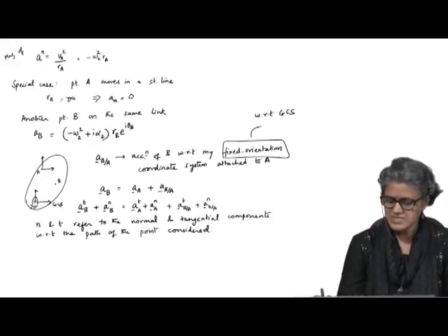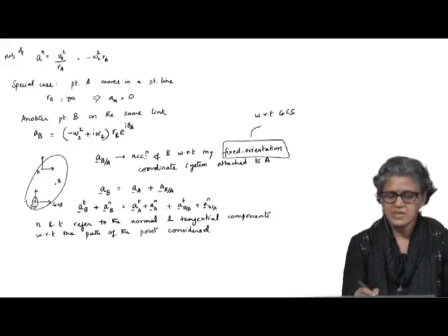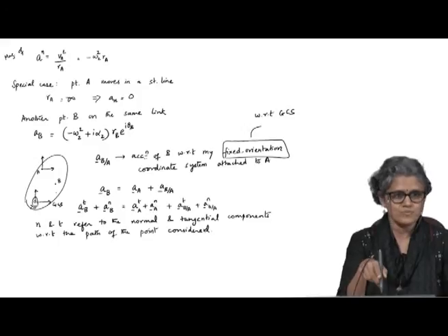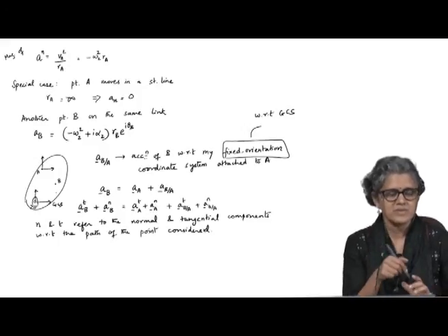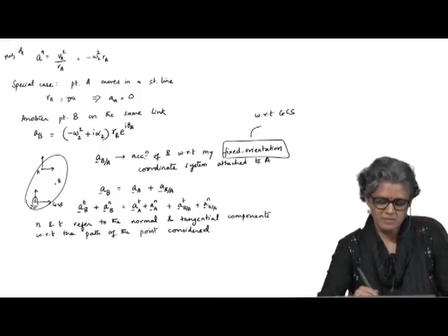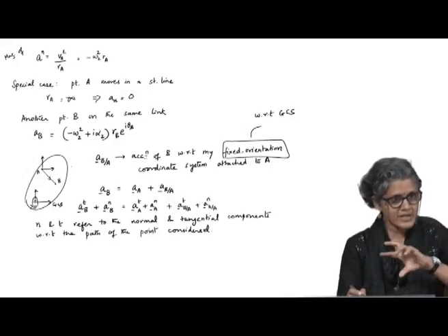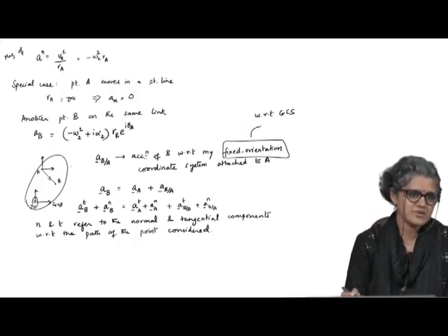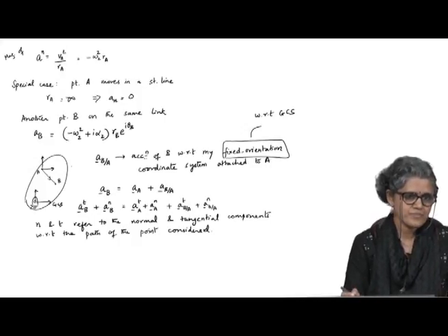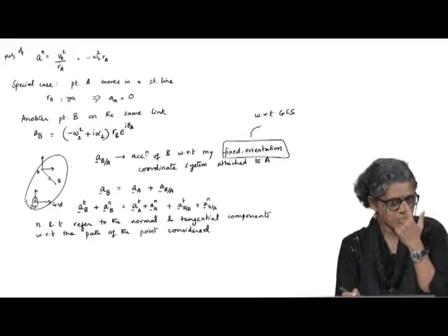And the tangential acceleration will be in the direction of alpha_2, 90 degrees. So, this vector AB is rotated 90 degrees in the direction of alpha_2 and scaled by alpha_2.